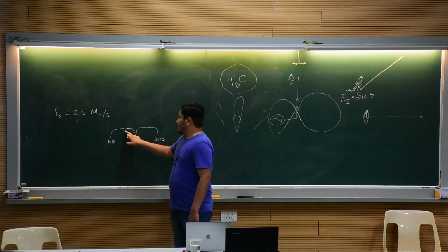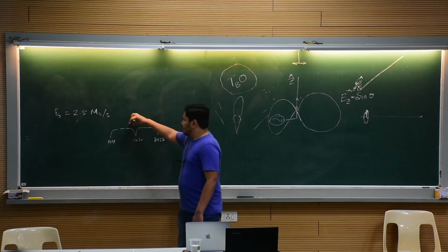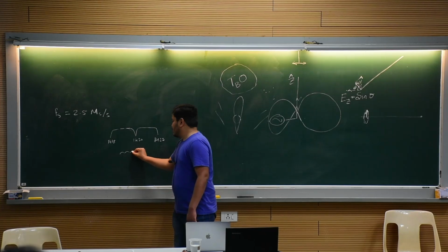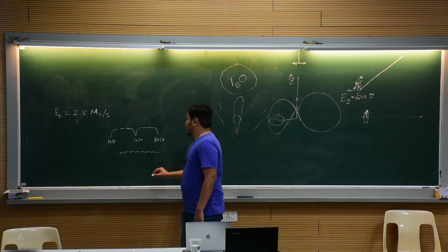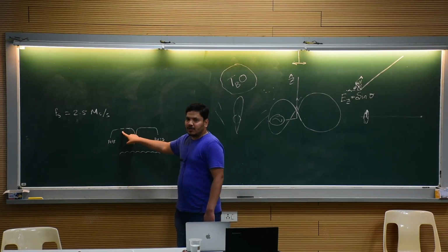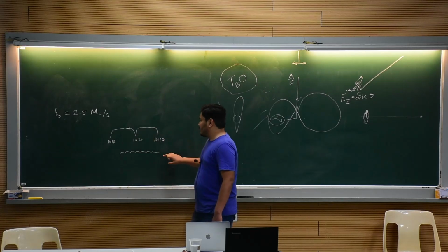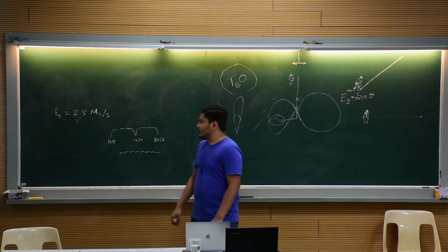But this is a very small window, and we want to measure a 4 megahertz band. So we'll have to tune it repeatedly. It will plot something like this. It will take only the most sensitive part of the receiver, and then it will shift, and you will get 4 megahertz worth of bandwidth. You will understand what I'm saying when you look at the plot.